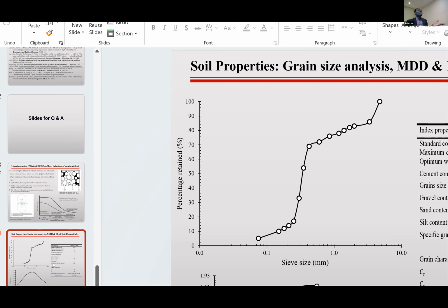But clearly we have to apply surcharge, right? And wait for a period of time for water to drain and all those kinds of things. Yes, I did, because when you apply the stress, of course, there was a drop in volume change. So you expect to compute Cc for sure. And what you observe is that the sequential hydration sample on the third day seems to show the highest volume change, and I'm saying that we can use that to our benefit. It means that if we apply the sequential hydration on the third day and then compact our soil layer, we're able to achieve higher density in the field.